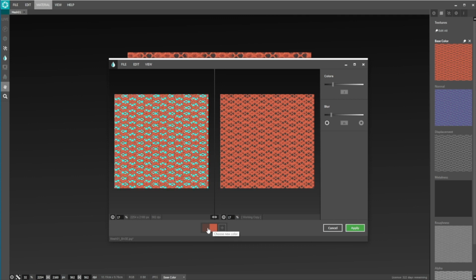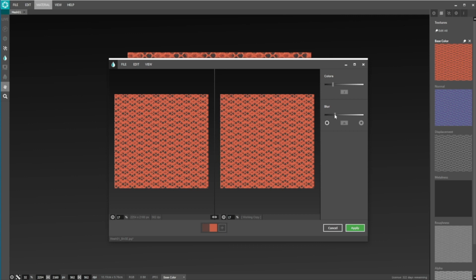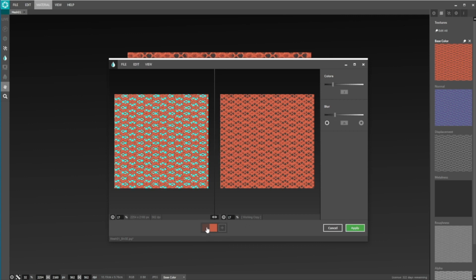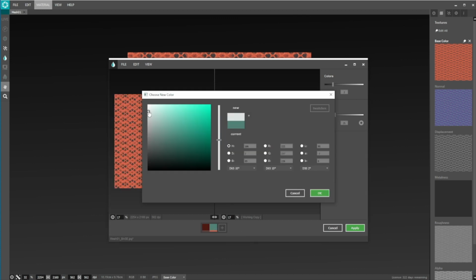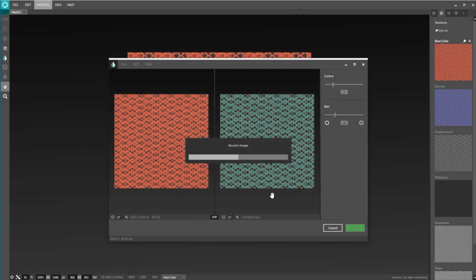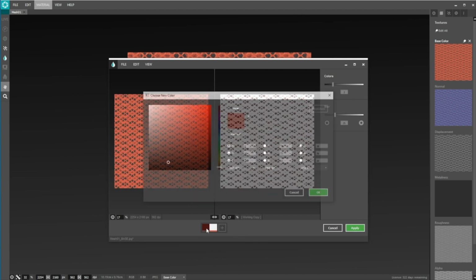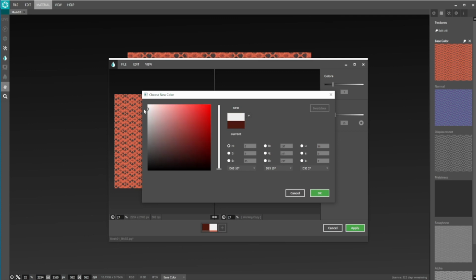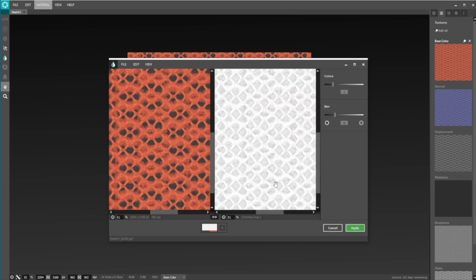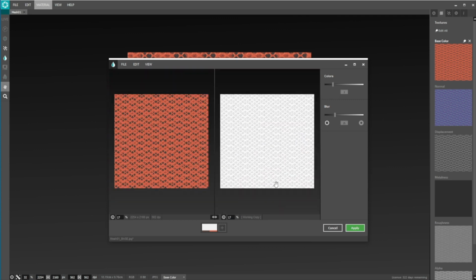Previously, we showed how to change your material to a nearly white color so you can recolor it quickly in Keyshot. We'll do that again for both colors in this material. Before we close the recolor tool, we need to perform one new step. Otherwise, Keyshot would still only be able to apply a single solid color to this material.